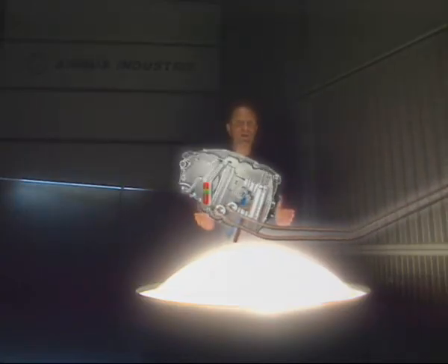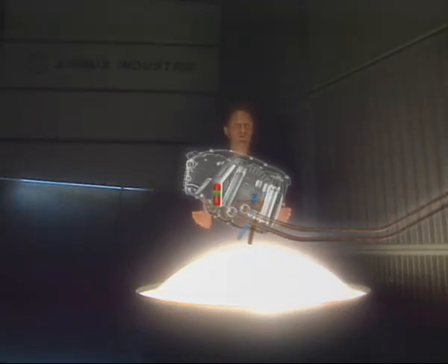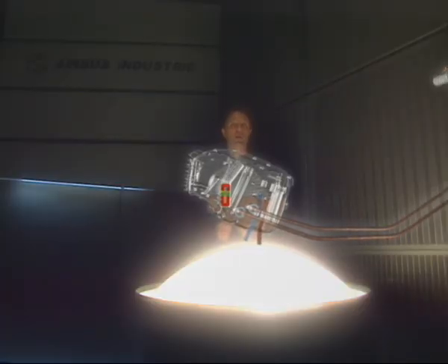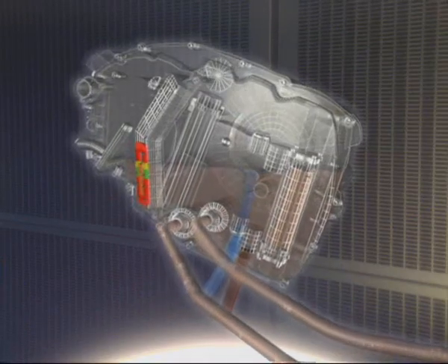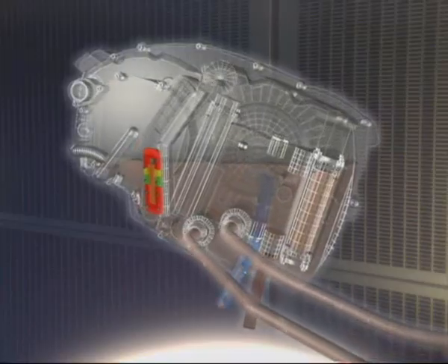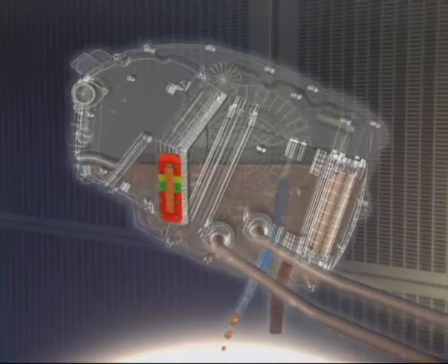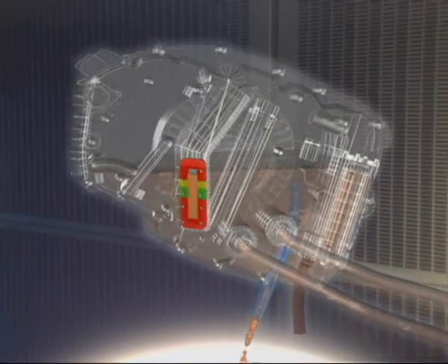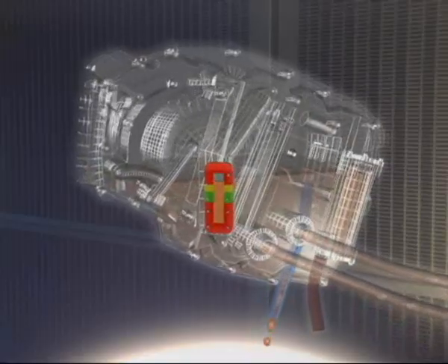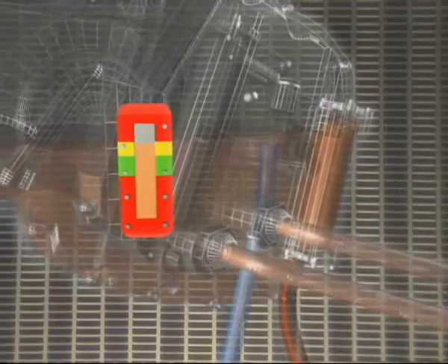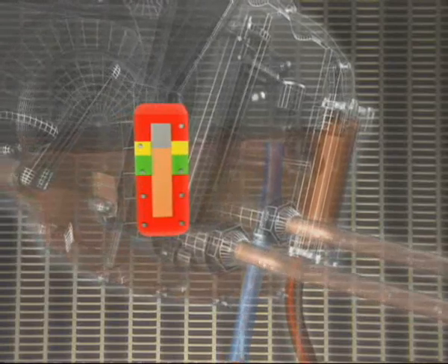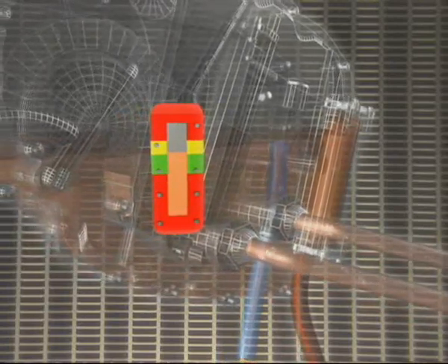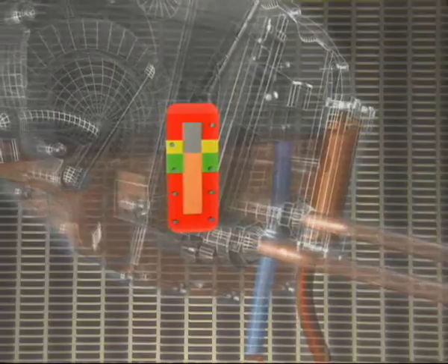Now the IDG case is being filled with oil. Once the oil level exceeds the top of the overflow standpipe, it flows outside the IDG through the overflow drain port. The top of the overflow standpipe corresponds to the top of the green band of the sight glass.